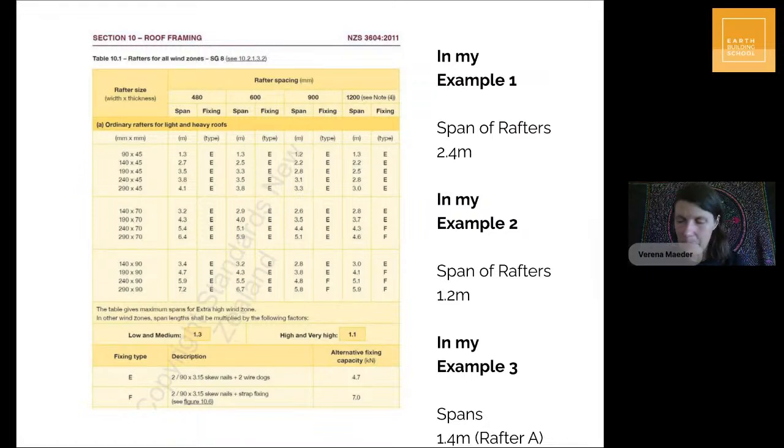And then for the other example with A and B, we again had a short span and a longer span. And up to you, I would probably make them look the same. So you need to size them for the longer span, which I think was 3 meters. And again, you would be reading down and seeing the closest thing to 3 meters.